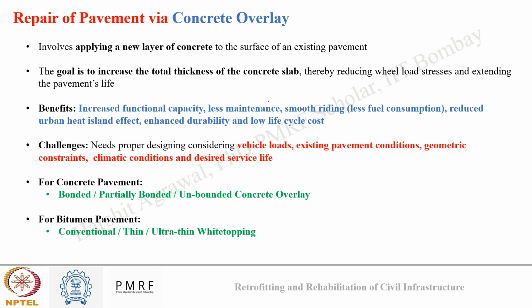Now, once we know the type of pavement distress and the extent of damage due to distress, we can go for repair. For pavement repair, one of the most commonly used techniques, after obviously filling the cracks that occurred due to distress, is the concrete overlay.